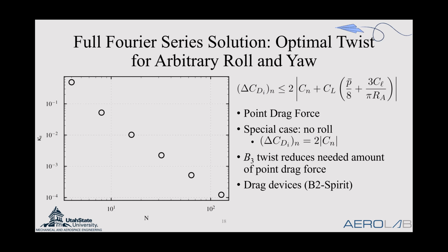So it doesn't make sense to optimize for roll or yaw. Those are your constraints to your problem, right? That's what's required for the flight mechanics for your particular trajectory or path you want to follow. That would be a requirement. If we were to optimize for yaw, I've done that, and all that does is give you the max yaw authority that you can achieve with your setup.